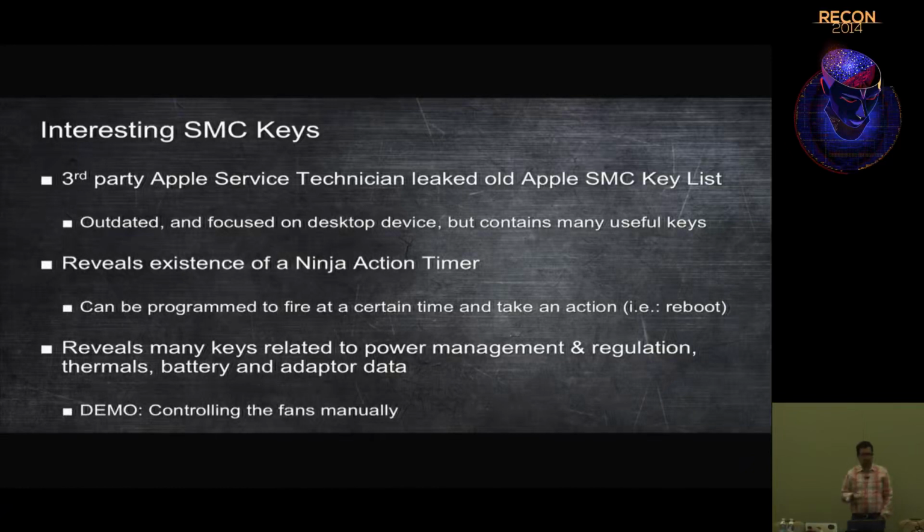This is actually used by a watchdog. So if there's a driver on the Mac that basically reprograms the ninja timer every 30 seconds, and the action is reboot, then if it doesn't get reprogrammed every 30 seconds, it's like a dead man switch, and your Mac will spontaneously reboot. So if it freezes and just runs at maximum CPU and nothing is happening, the driver stops running, the ninja timer will count down to 0, and then the ninja action will happen, which is basically the reboot. So it's got a lot of keys here to manage basically thermals, fans, and I'll do an example of how those work as well.